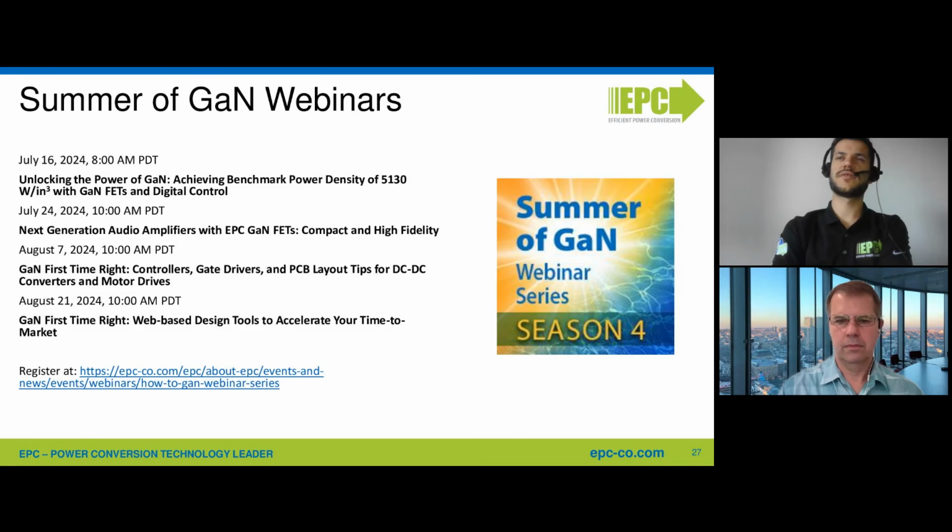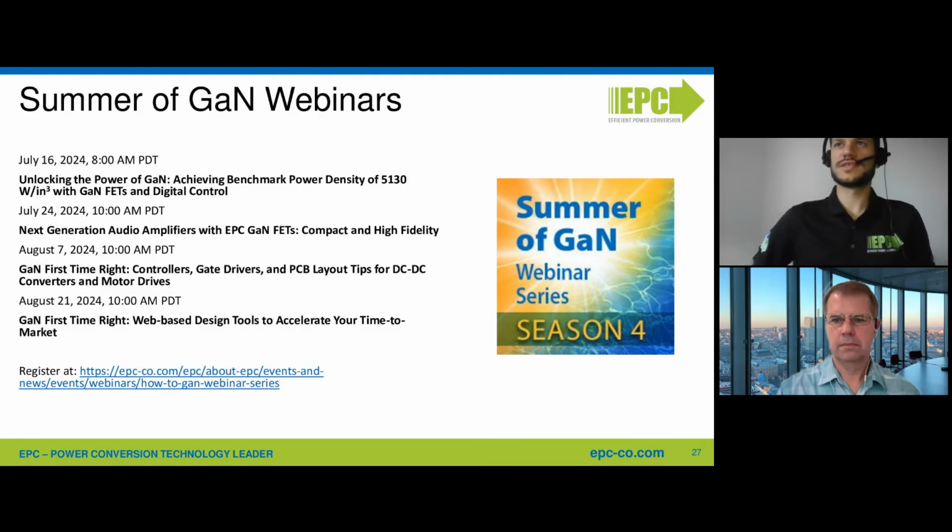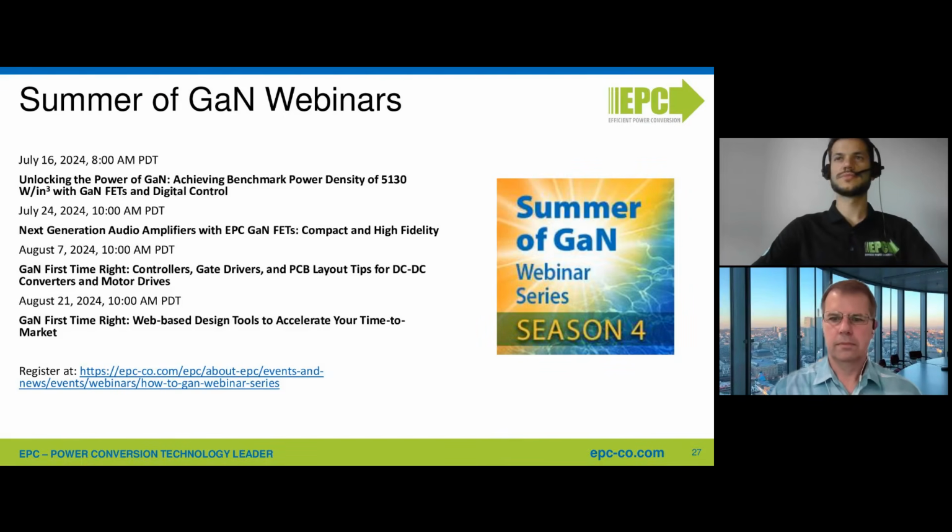The con is that the reverse conduction in the GaN has a higher voltage with respect to a diode. So when a motor is rotating with its own inertia and is acting as a generator, the gallium nitride inverter still has reverse conduction to rectify. So it works the same as a MOSFET inverter, just a little more lossy.